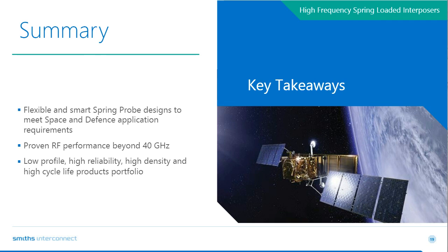Thanks, Dennis. So, in summary, we introduced 3 spring probe designs and showed some different methods of construction for interposers. We gave a few examples of how interposers can be designed into RF and digital applications. And we discussed the importance of simulation confidence. In the simulation example, we demonstrated that we had good measurement correlation to the simulation and performance well beyond 40 gigahertz.